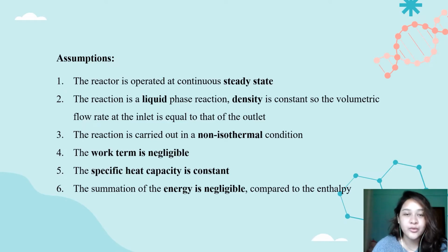For the assumptions that will be applied for the calculation part, the reactor is operated at continuous steady state with liquid phase reaction where the density is constant, so the volumetric flow rate at the inlet and the outlet are equal. The reaction is carried out in a non-isothermal condition where the work term is negligible and the specific heat capacity is constant, where the summation of the energy is negligible compared to the enthalpy.